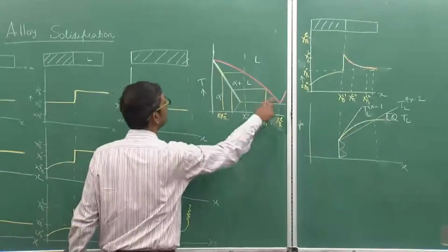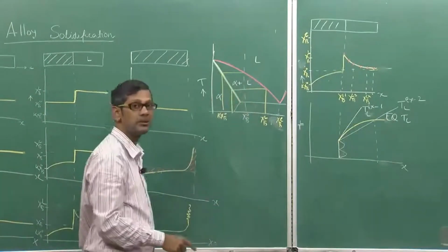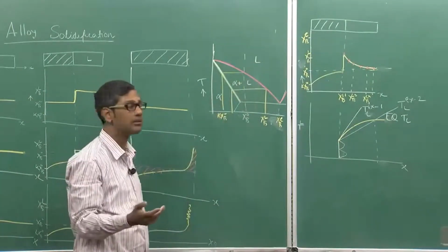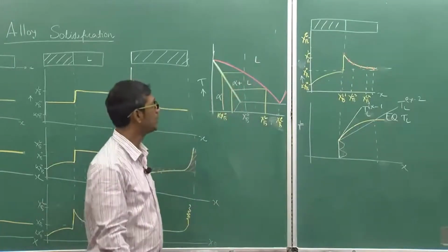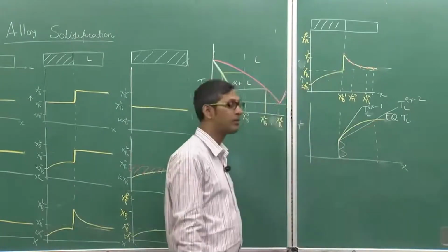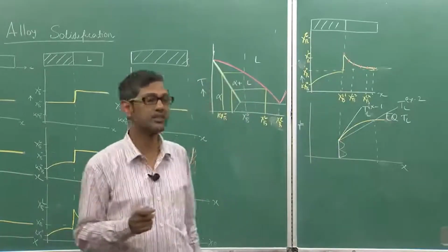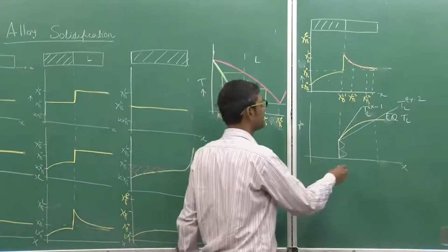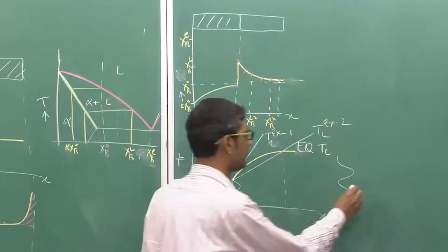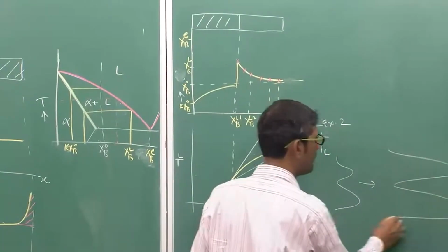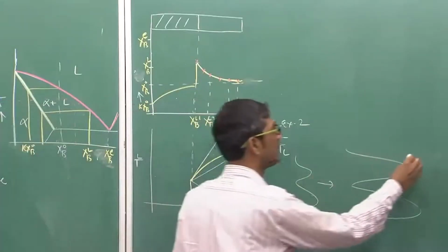Remember, anything below the equilibrium liquidus temperature, solid can remain present, because this is the region between alpha plus liquid. Anything above, it is only liquid. So, above this temperature only liquid can remain; below this temperature, both solid and liquid can remain. Because the temperature here is lower than the equilibrium liquidus temperature due to experimental conditions, we are going to develop serrations, or features, on the surface, and these features will grow as time goes on. They will become bigger, much bigger.